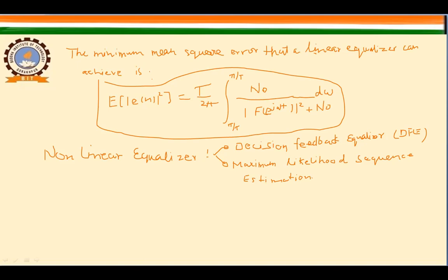The reason for choosing the non-linear equalizer over a linear equalizer is that the performance of the linear equalizer on channels that exhibit nulls is not effective. So the noise enhancement in this region and long impulse response are the problem. The basic reason for this problem is that linear filtering processes the noise together with the signal, which is causing the noise enhancement problem.